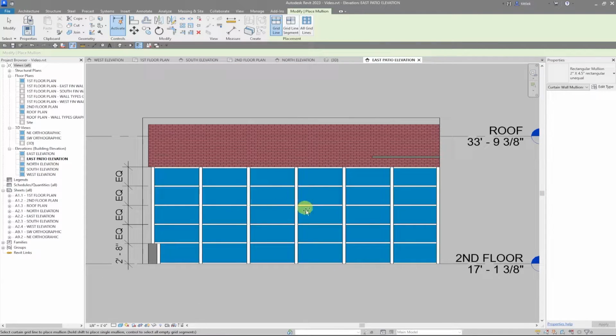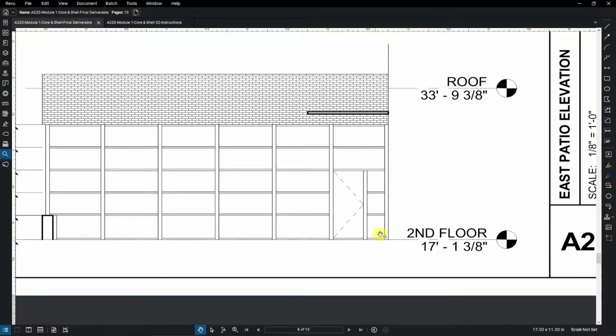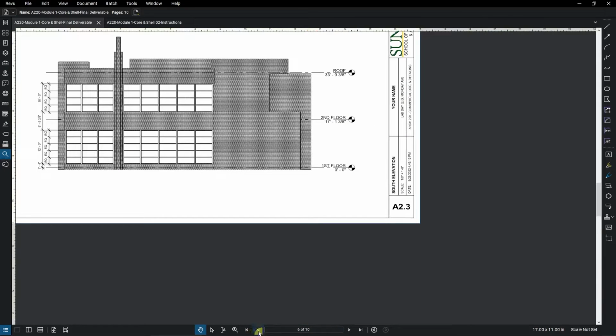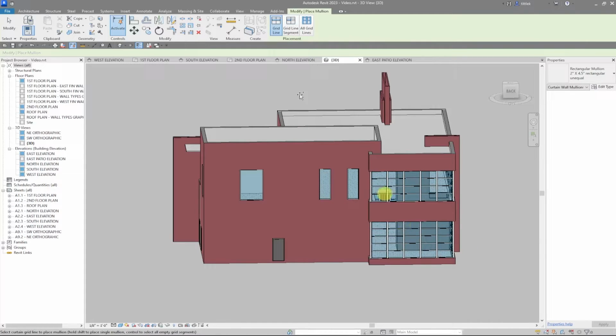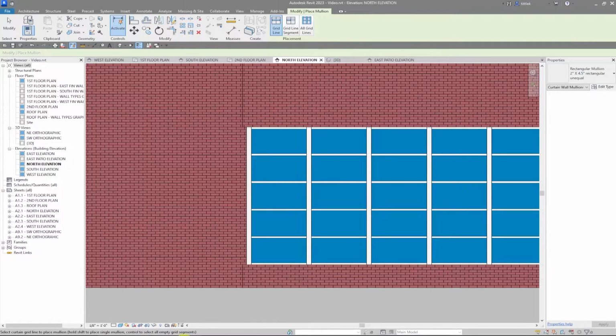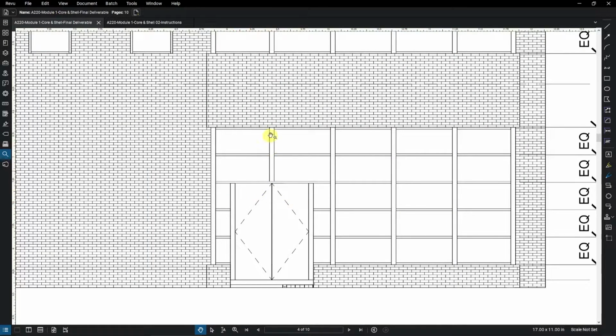So the next thing I'm going to do is start to create these doors in the curtain wall. I'm going to start with the north elevation, our main entrance to this building. So I'm going to come around here to this elevation here. So that's our north elevation. To do this here, I'm going to utilize that reference plane again. So this door is centered on this mullion, and this mullion's location is set by dividing these all equally. Now again, we do not have these actually divided the proper way according to the plan, and that is why we're going to start setting this all up.